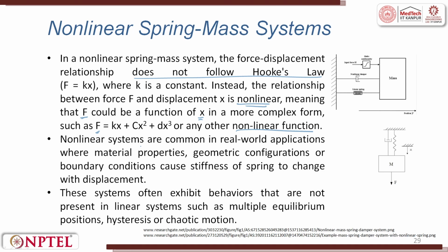Nonlinear systems are common in real world applications, where material property, geometric configuration or the boundary conditions cause the stiffness of a spring to change with displacement. Nonlinear is reality. These systems often exhibit behavior that is not present in linear systems, such as multiple equilibrium positions, hysteresis or chaotic motions.